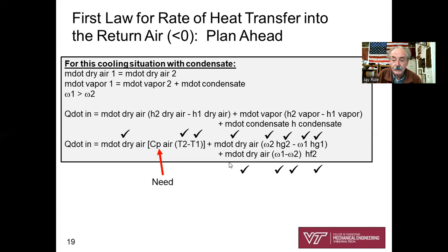It is an outflow. So let's think about our system without going back in the slides. We've got one inlet, and we have two outlets, right? We've got the air vapor mixture going to the rooms, and we've also got an outlet, drip, drip, drip to the condensate. So that's what this term is all about. So this is correct. And I will endeavor to go fix my static slide before I post these, the correction.